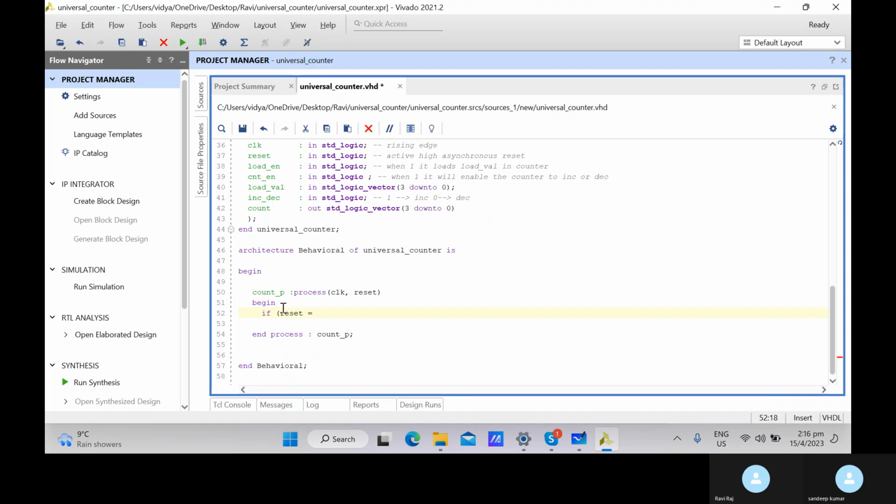Reset exactly right. So take one. Then at reset, we always initialize the value output. So there's only one output, right? So we initialize that output. And how can we make it zero, all bits zero? What should we write? Others equal 0. Yeah, others zero, I remember. Then else if it's a rising edge, so we write clock to 1 and clock tick event.